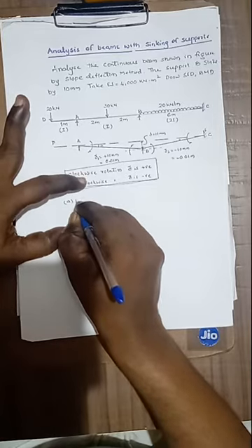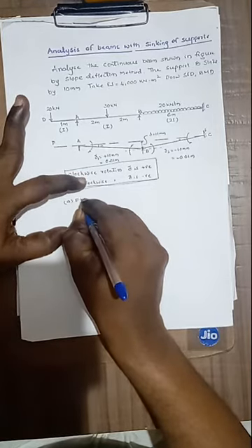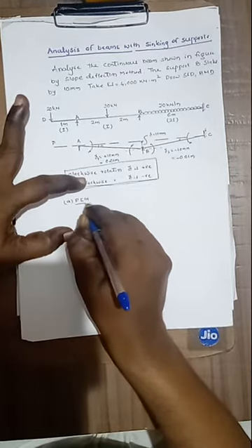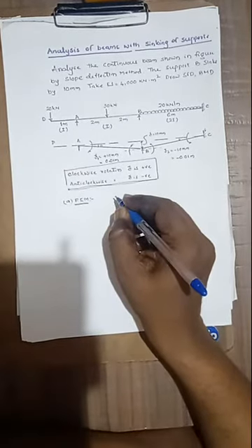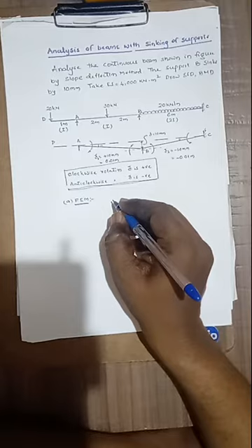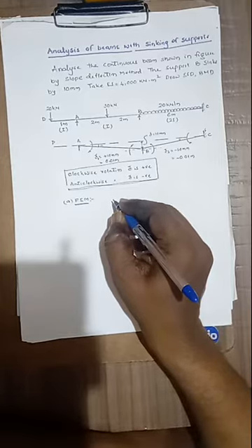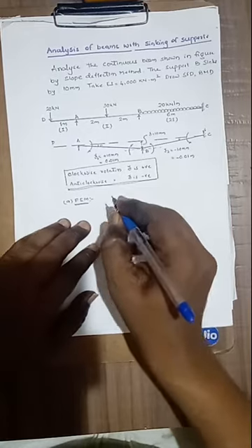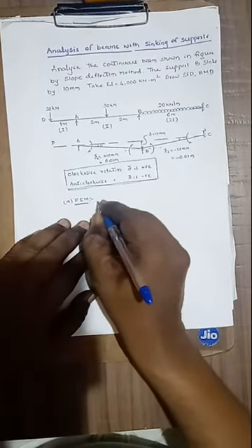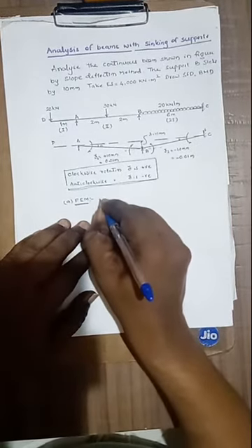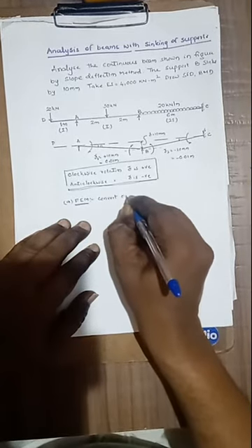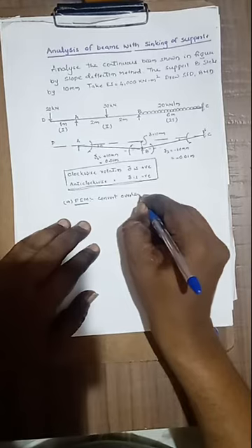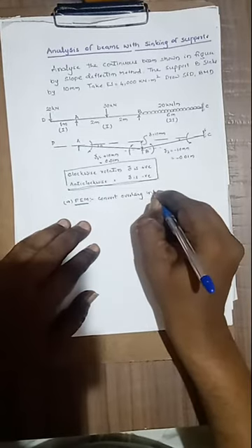Then the fixed end moments, FEM, for each span. There are 3 spans, but the span DA is extended beyond the support and is overhanging. No need to write the fixed end moment for the overhang. Convert the overhang into a resisting moment.